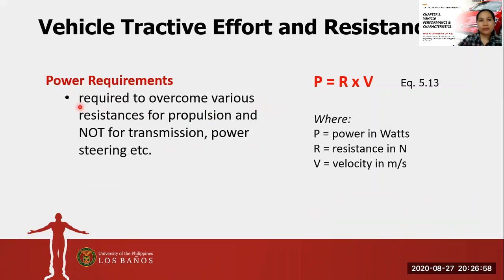The power required to overcome the various resistances is for propulsion, and not for transmission, power steering, etc. So the power requirement is equal to the resistance times the velocity in meters per second.